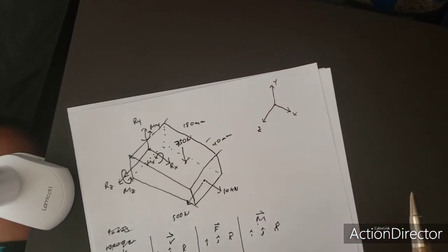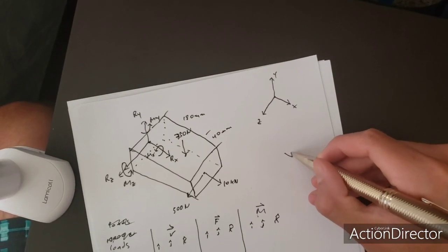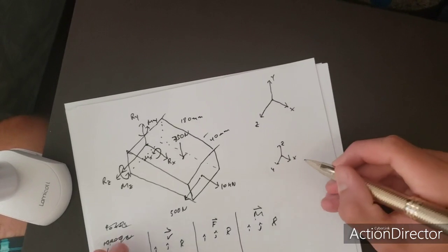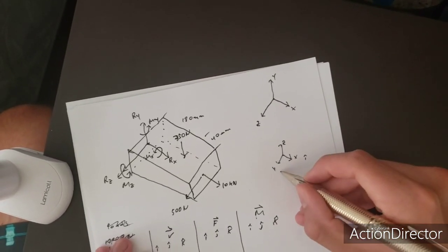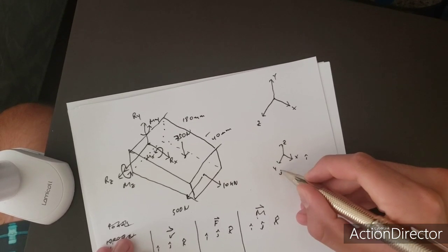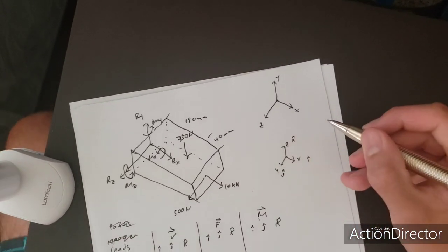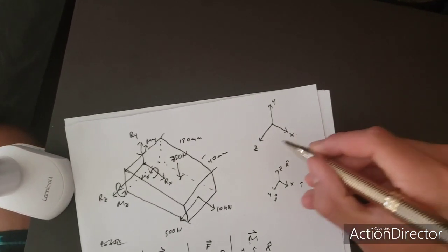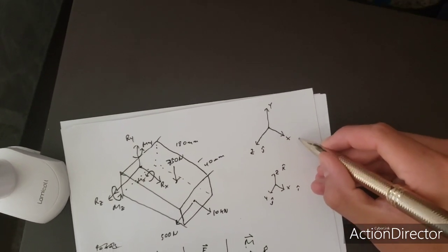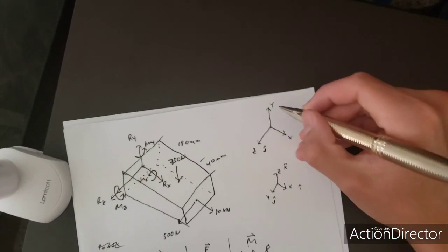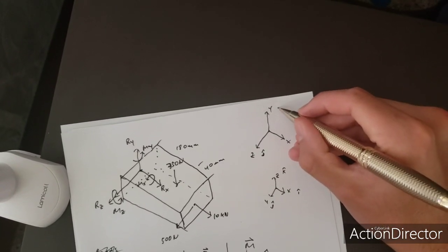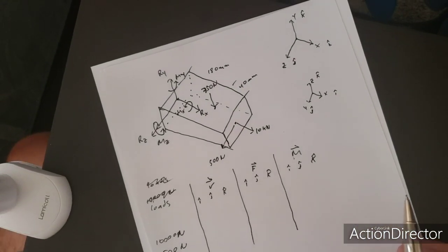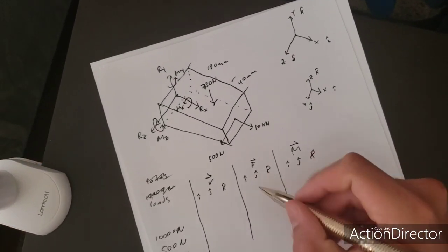Because I've always been used to seeing this one being the X, this one being the Y, and the elevation being the Z, I want to stick to having the X as the I component, the Y as the J component, and this one as a K. I'm used to seeing it in that form. So instead of assigning the Z with the K, I'll assign it with the J, and the X with the I component, and the Y with the K component. And then here again, I'll just make a little note so I won't screw up the data, having it backwards.